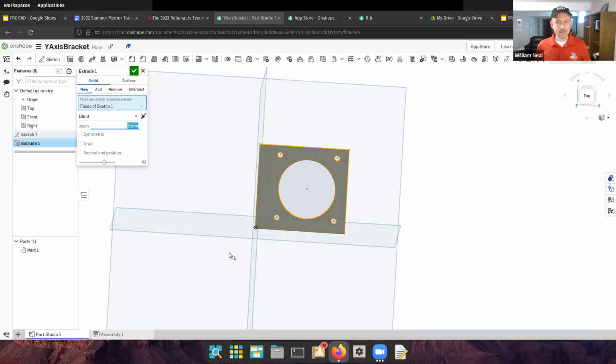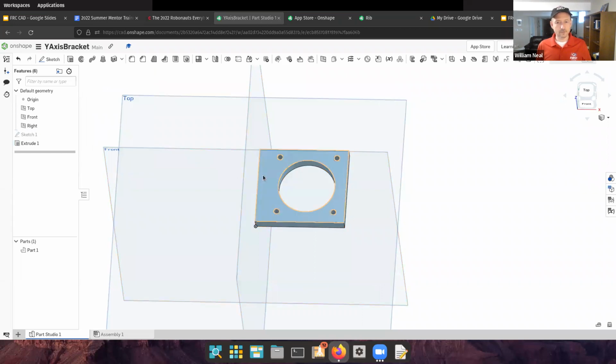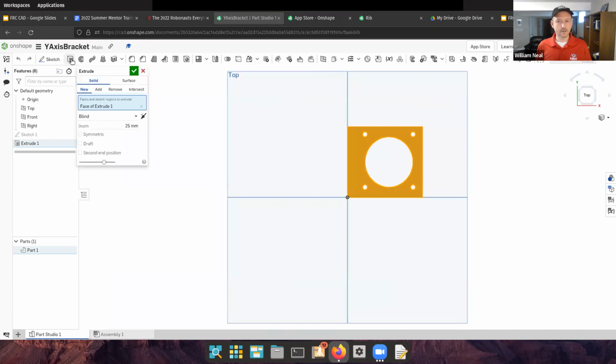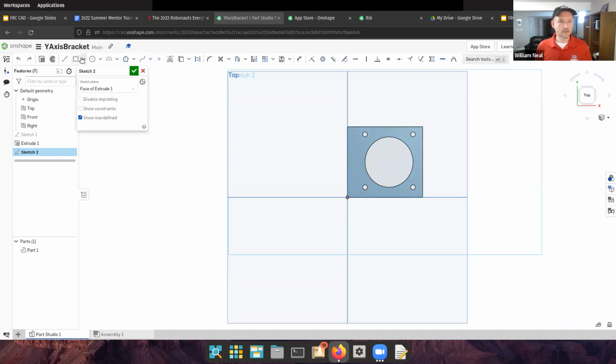So now the next thing I may do, I'm going to go back onto this surface here. Once I'm done my extrude, I'll select this top surface, and I'm going to make a little drawing here, a place to actually attach the motor onto my 3D printer. So let's make a place to do the attaching. A simple rectangle should suffice. Make a sketch on top there. Oops, not an extrusion, a sketch rather. And you see I accidentally unselected my surface, so I select it first. Make a sketch and a simple rectangle, maybe right here.